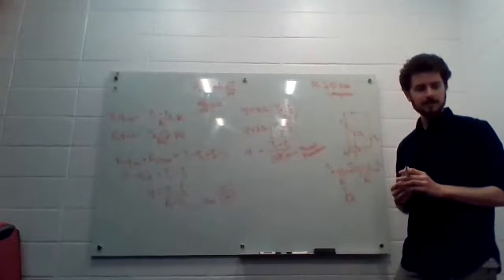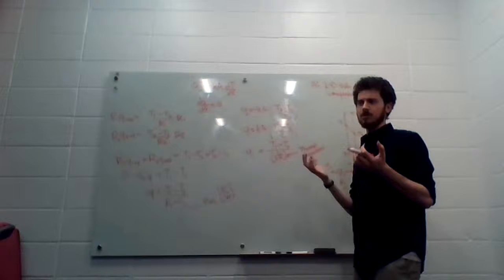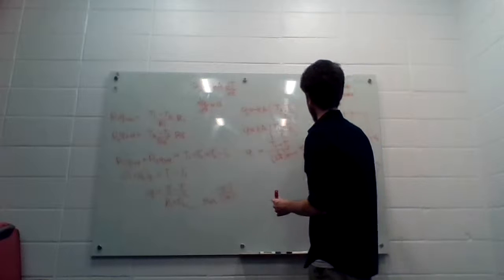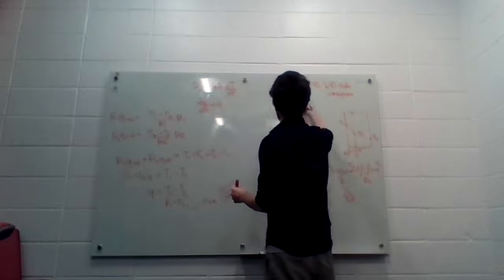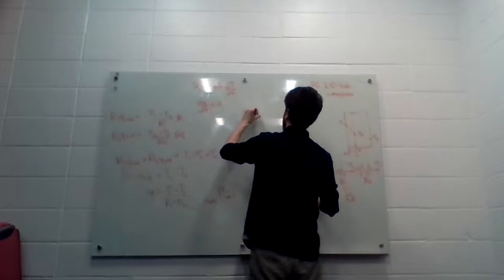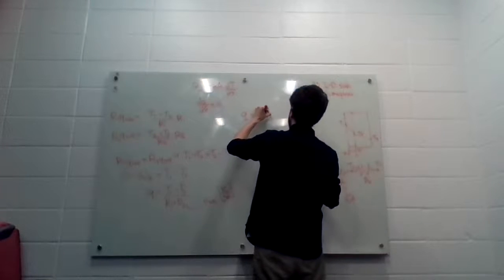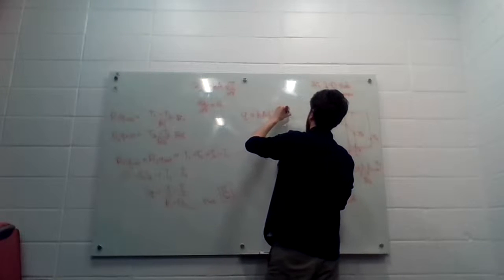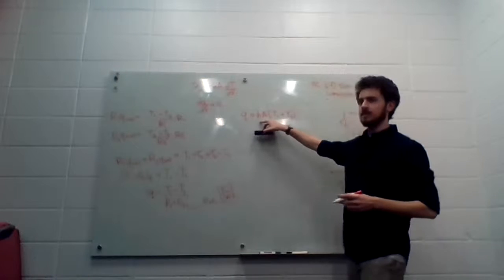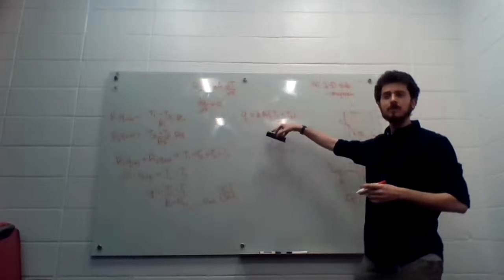The last thing I wanted to say is we've been doing thermal resistances for materials, just solid, intuitively we're thinking about solid slabs of things. If you go back to where we started class, I'm going to get rid of this. What came before Fourier's law? Newton's law of cooling. Q equals h A delta T, make it T1 minus T2. We dealt with Newton's law of cooling a little bit. h is your heat transfer coefficient. So it describes, what are the units for h? Do you guys remember that?